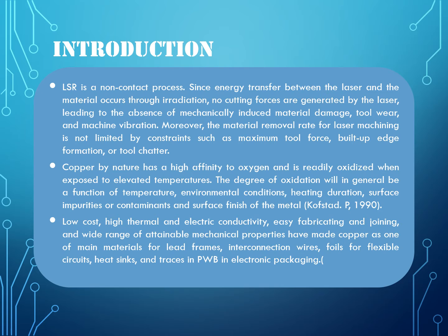Copper by nature has a high affinity to oxygen and is readily oxidized when exposed to elevated temperature. The degree of oxidation is a function of temperature, environmental condition, heating duration, surface impurities or contamination, and surface finish of the metal.